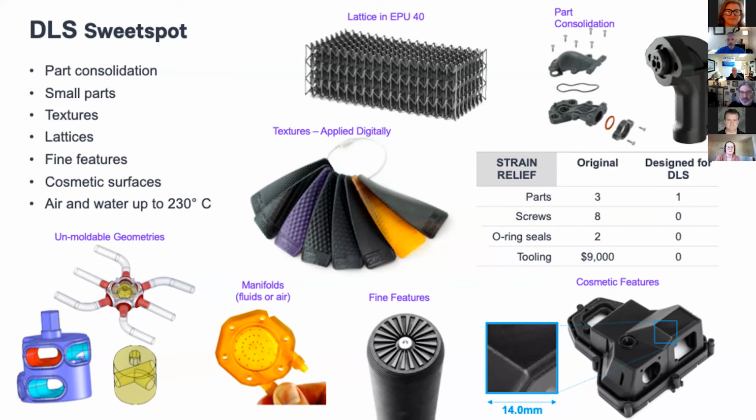But one of the biggest strengths that I always say in Carbon is part consolidation is huge. This is a very big win. Can we take something that is X amount of parts, has a couple of items that are sourced and needs hand labor to be put together? Can we relook at that design and consolidate down to one part that performs better? We've gotten time back up front that we can really put into the design and making a better performing product and avoiding cutting a tool.